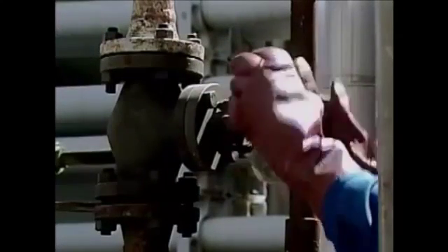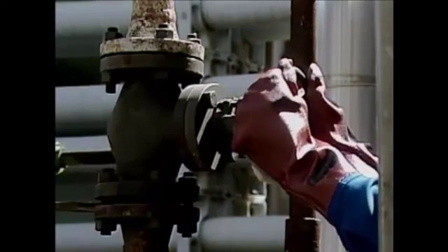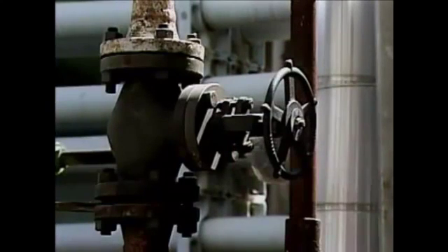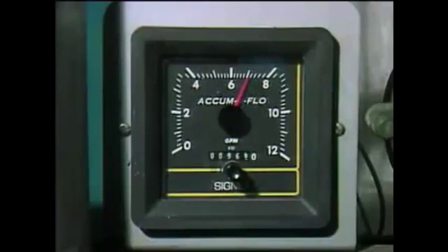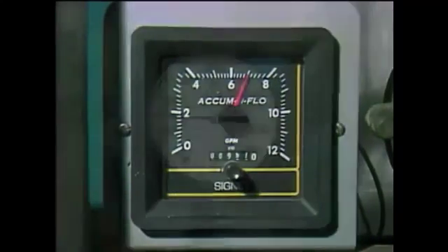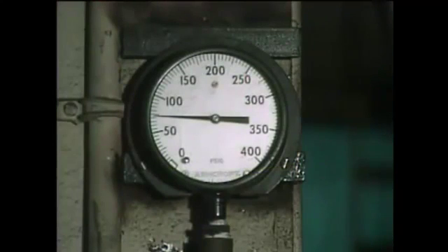Adjusting control valve settings is a common way to control the flow rate in a system equipped with centrifugal pumps. But besides changing flow, these adjustments may also affect other variables in the system. Adjusting control valve settings to change flow will also affect pressure, since flow and pressure are so closely related.